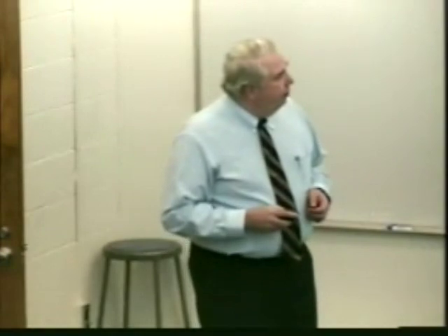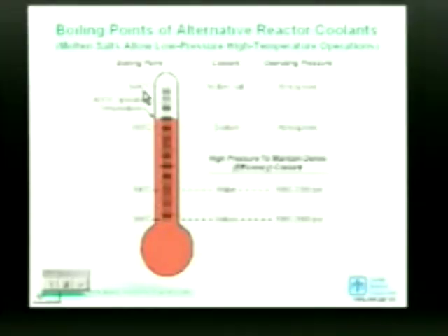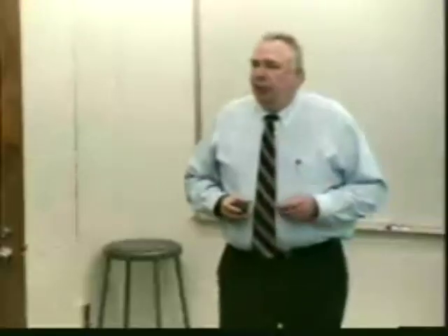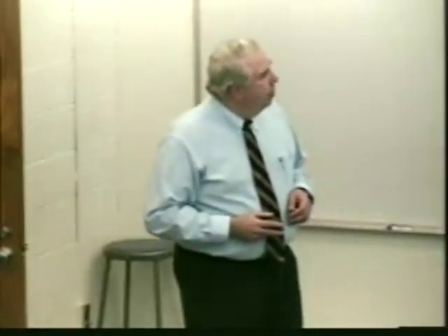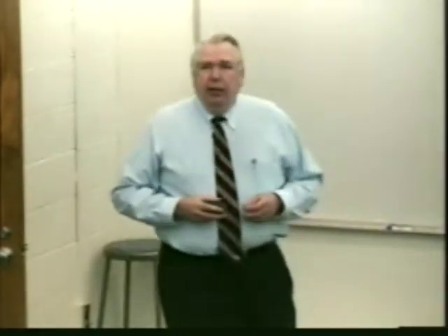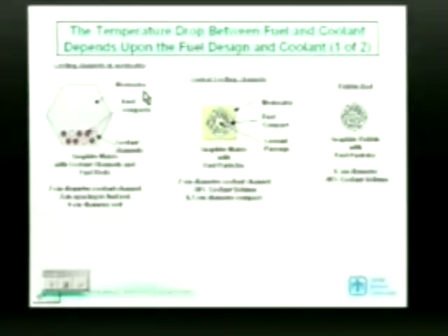If we use this type of coolant, we can safely say the coolant is not going to boil. So we have a nice liquid coolant, very low vapor pressure, a fraction of an atmosphere during any kind of conceivable operation. I'd now like to discuss the fuel and the implications of the fuel and using a liquid coolant. I make the following observation. The temperature drop between a fuel and a coolant depends upon the fuel design and the coolant.